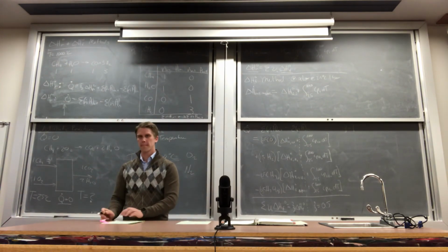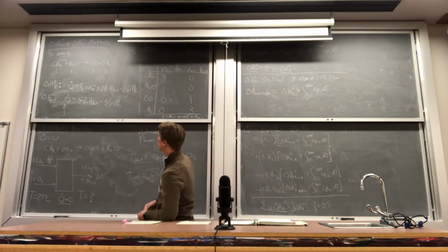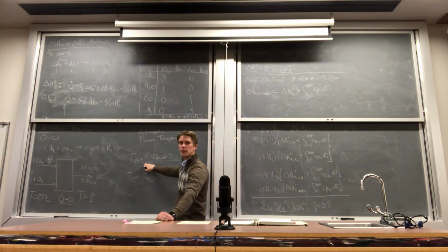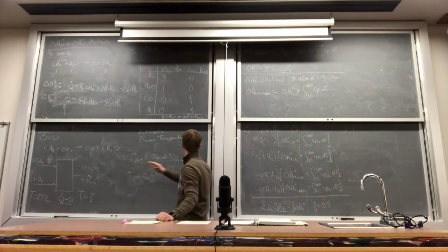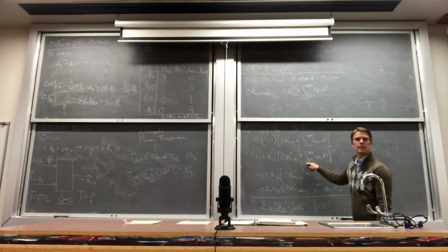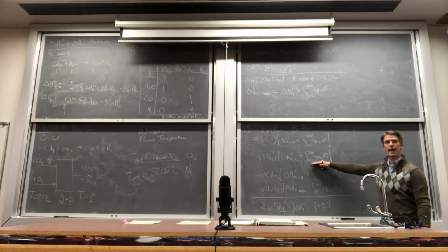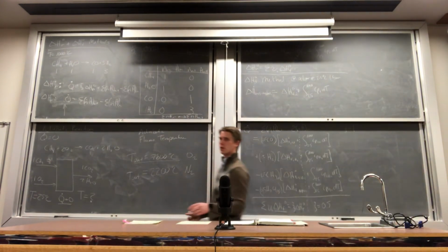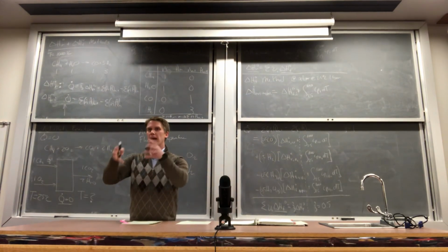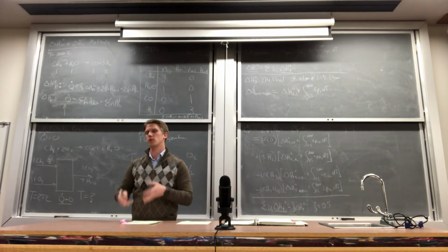Just to clarify, on this type of problem, it'd be like a nonlinear solver in the case of MATLAB? If you assume a constant heat capacity, you might be able to set this up as a linear problem. But if you're solving it using correlations for your heat capacities for your outlet, then it'll definitely be a nonlinear solver. If you do a non-constant heat capacity, which you definitely should do, it has to be nonlinear, because it would be T out to the 4th power minus T in to the 4th power, and you'd have all of those for all the different species. So it's a big problem.